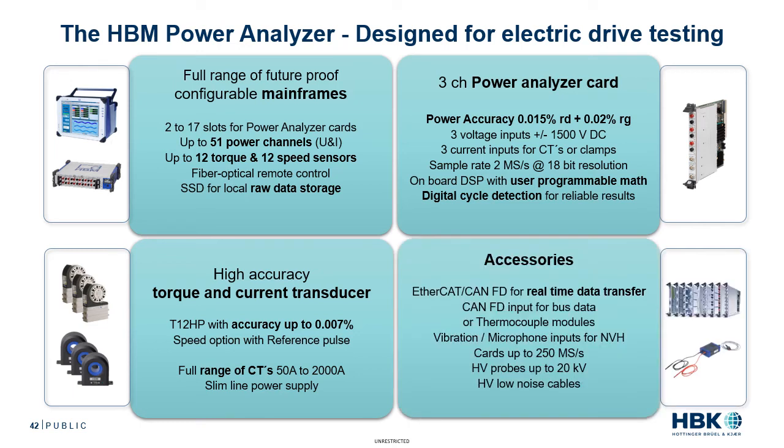And then lots of accessories from EtherCAT, CAN-FD for real-time data transfer, CAN-FD for input for bus data or thermocouple modules, vibration and microphone inputs for NVH, and cards up to 250 million samples per second, high voltage probes up to 20 kV, and high voltage low noise cables. It's a complete power analyzer solution.